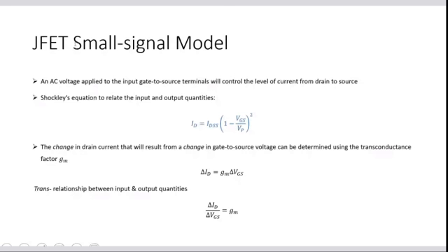For resistance we have R is equal to V by I, whereas for the conductance, it is exactly the opposite. It is I by V. That's why gm is equal to del ID divided by del VGS. Del means nothing but a small change in the drain current, small change in the VGS. This equation actually explains that.